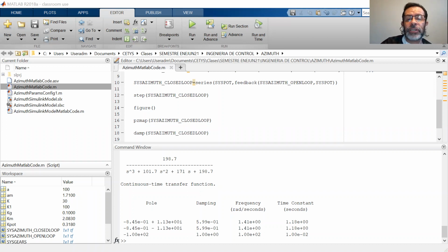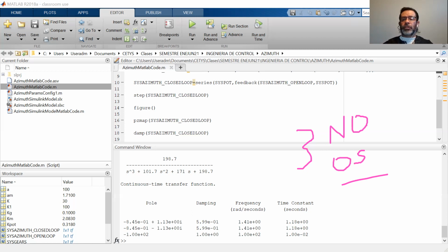The characteristic of these is that there is no overshoot. So for critically damped or overdamped, you're not going to go over the desired value. That's why it's exponentially trying to get there. It's going to be slower, but you're never going to go past the value.